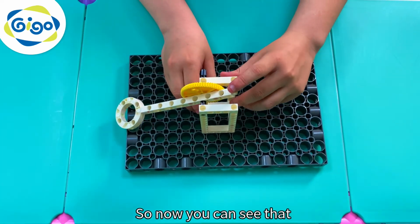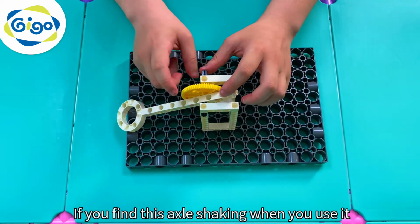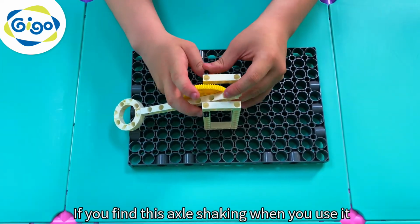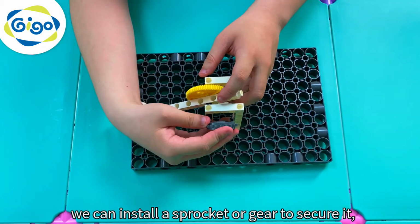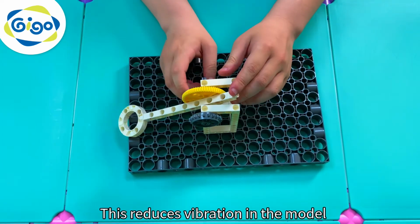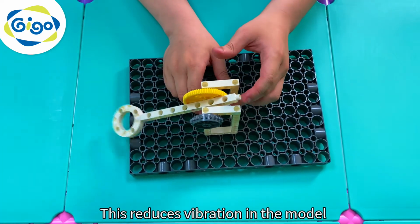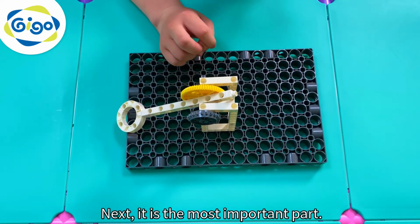So now you can see that the catapult structure is really quite basic. If you find this axle shaking when you use it, on the right hand side, we can install a sprocket or gear to secure it. I use a sprocket here. This reduces vibration in the model that could shake it apart after several uses. Next, it is the most important part.